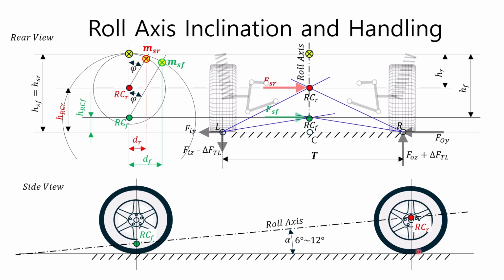This can be mitigated by increasing the front wheel load, or by utilizing the camber angle created by the suspension links due to the roll of the sprung mass. Increasing the front wheel load reduces the friction coefficient of the front wheels, thereby reducing the tendency toward oversteer. Furthermore, by increasing the camber angle of the outer wheel, due to the roll of the sprung mass, the camber thrust of the outer wheel can be utilized to support relatively large lateral forces with low tire slip angles. This video briefly examines the principles behind this.